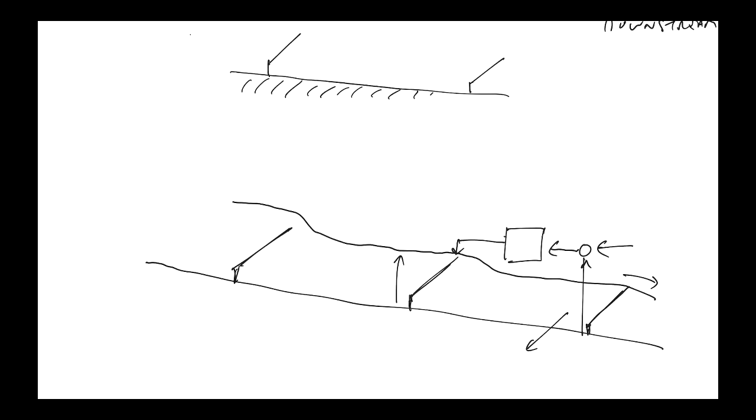So what happens when there's increased load downstream, or a farmer starts to draw water from the channel, is that the water level drops. It's just a bucket, if you like, and I start taking water out of it, more than's coming in, so the water level drops. And so you get a reference error, and the controller takes action by increasing the flow.